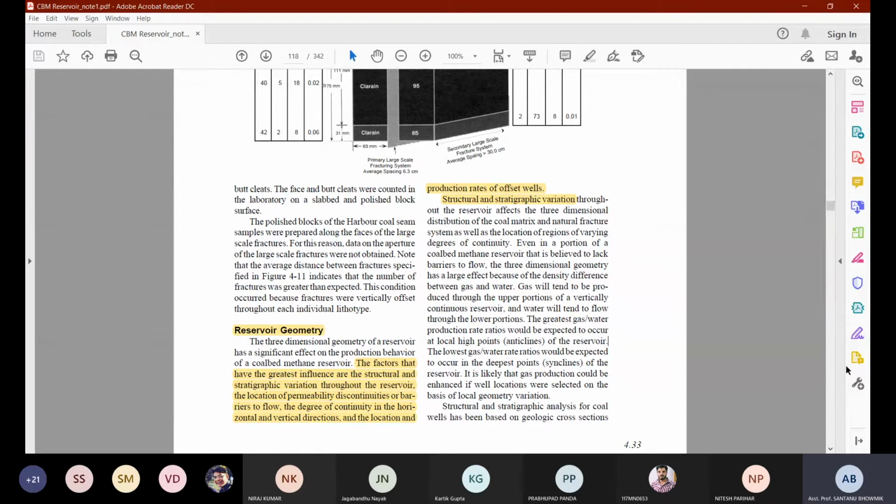Why? Because if you can remember, in the hydraulic fracturing process we have taken some assumptions that the major principal and the minor principal stresses are perpendicular, and one of them is going to be parallel to the borehole axis. But that is an assumption only. That may not be true all the way in situ. Why? Because you know that whenever there is a discontinuity, the major and the minor principal stresses are going to orient depending on the surface of the excavation.